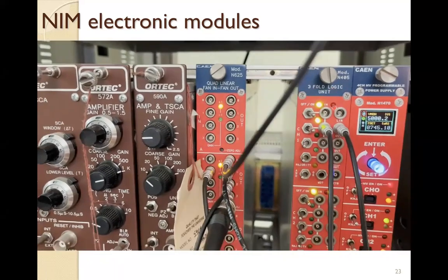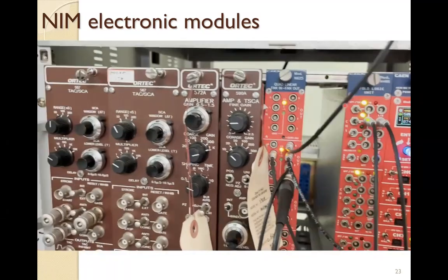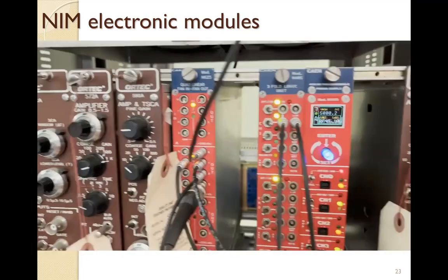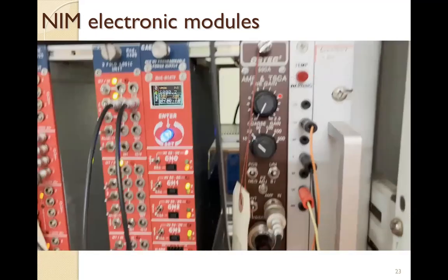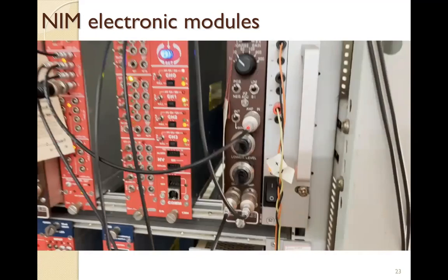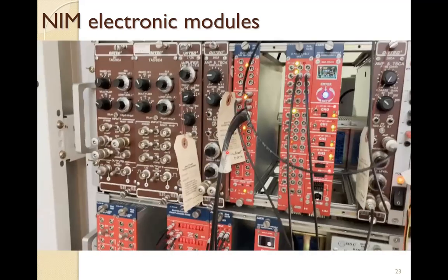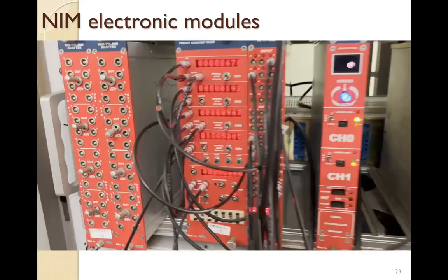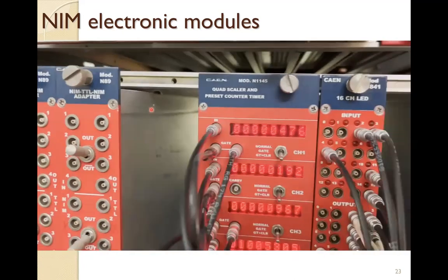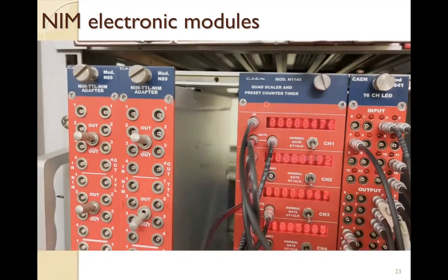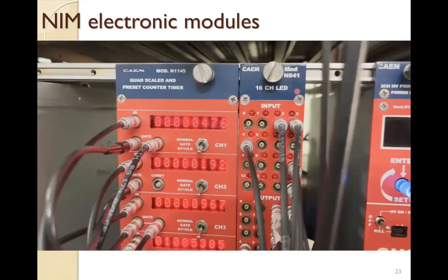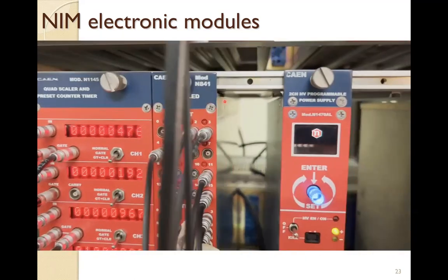3-fold logic unit. You can see these modules I have talked about in the circuit diagram. This is a quad linear fan-in fan-out module, and then this is SCA. TSCA means timing SCA, single channel analyzer. And there are some other modules, TAC, time to amplitude converter, NIM to TTL converter, NIM TTL adapter, you can see, and quad scalar. Scalar means counter basically, and 16 channel LED. LED stands for leading edge discriminator.